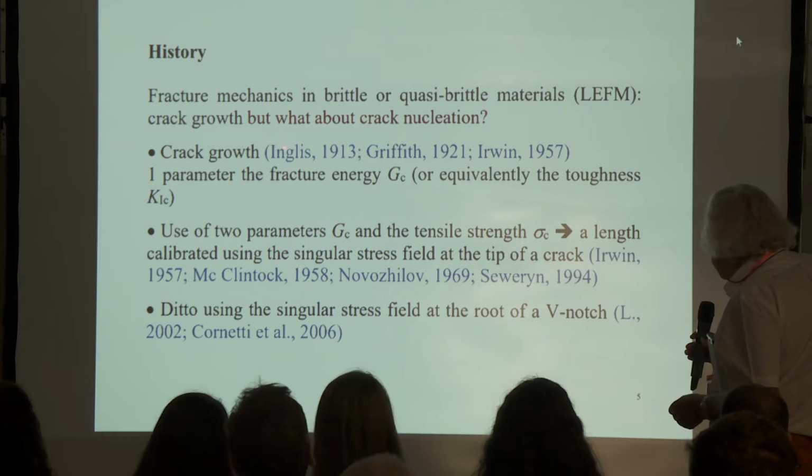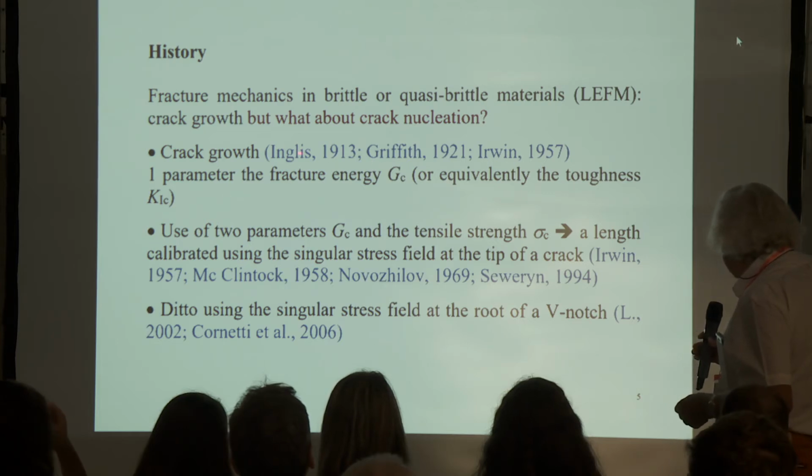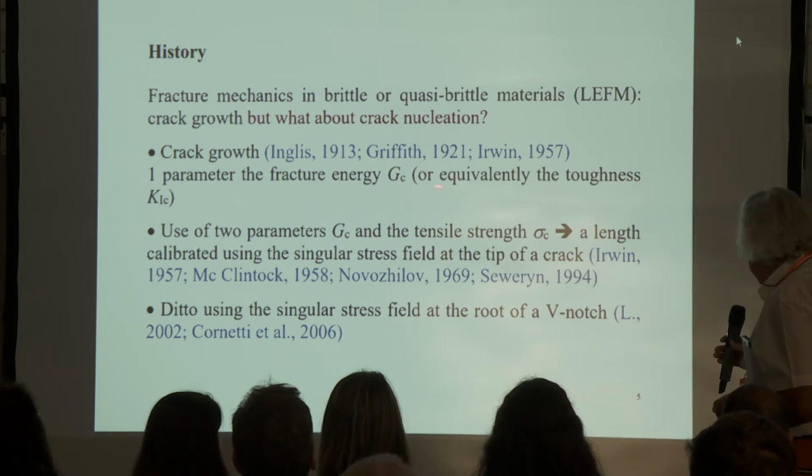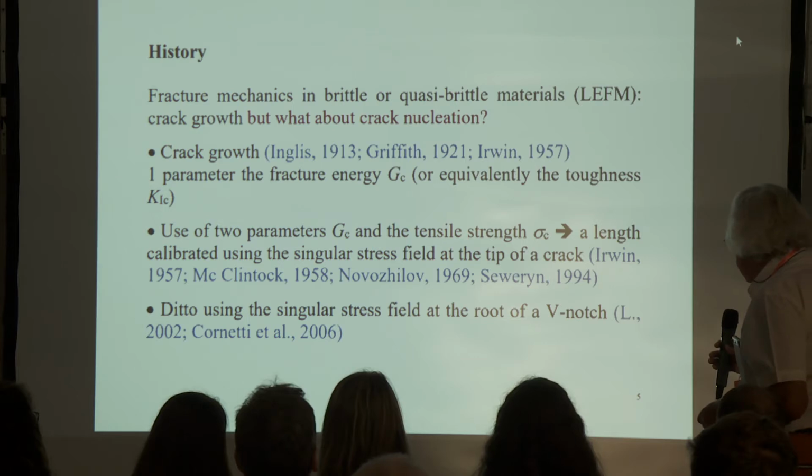Just to cite three famous names involved in crack growth: Inglis, Griffith, Irwin, everybody knows these names. The specificity of this theory is that it involves a single parameter, generally called Gc, the fracture energy, or equivalently the toughness, Kc.